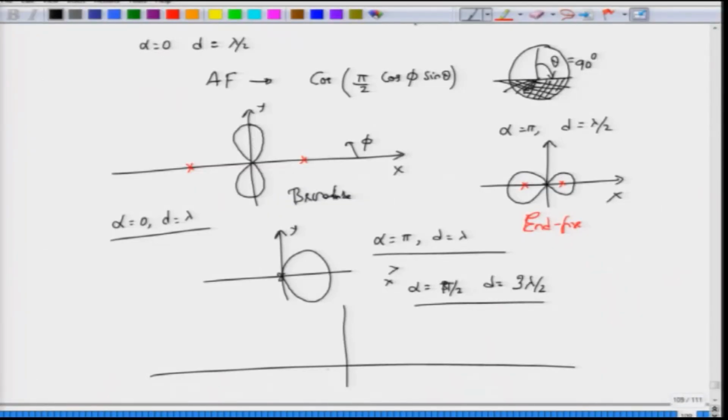What happens when you have n number of antennas, okay, all of them in phase located here? Then you can show the array factor would actually reach a maximum along a direction, and then the side lobes would actually be very small. Okay. So, the magnitude of the array factor, which essentially looks like a sinc function, is the basis of what is called beam forming.